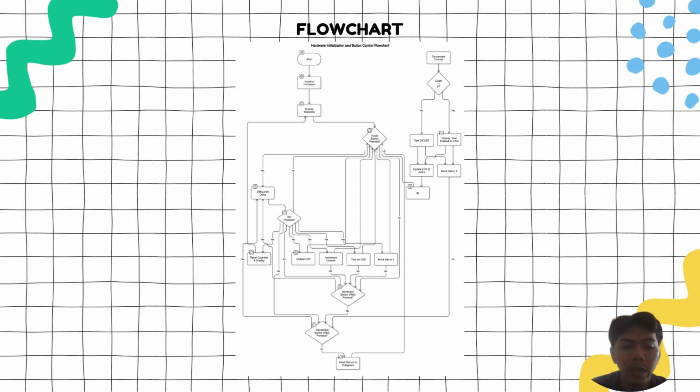After decrement, if the count is 0, the LED is turned off and the total is displayed on the LCD. If the count is not 0, the system updates the LCD with the count value. It essentially tracks change and updates the display.